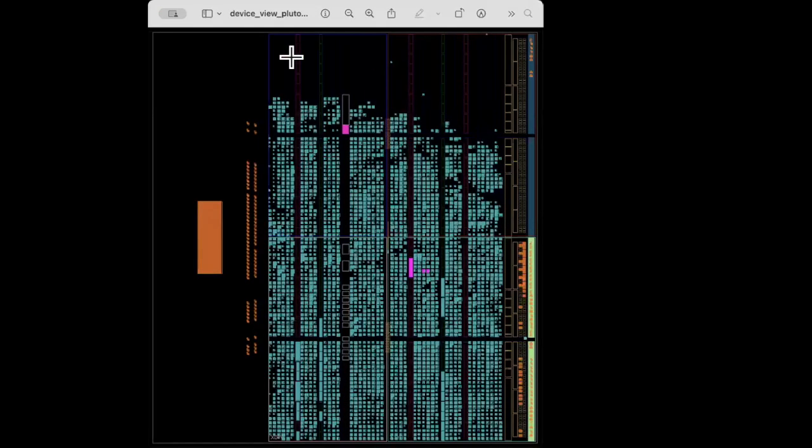Okay, so what you should be seeing is a bunch of cyan, or weird blue-green, blocks, and the whole image is the Zynq 7010. So this is literally the implementation. This is a visualization of where all of those lookup tables, where the BRAM, where all of the resources are allocated. I tried to get it to be color coded, but when you zoom all the way out, all the colors kind of blend together. So you can't see what is the reference design and what is our custom code.